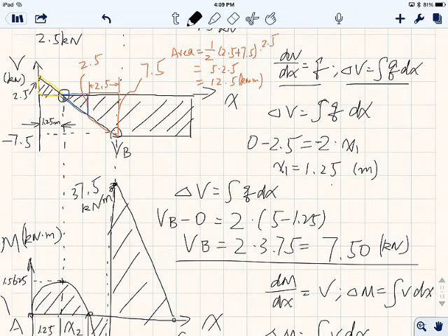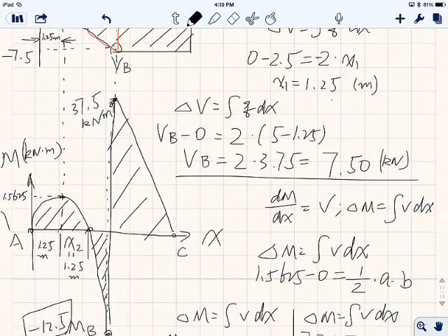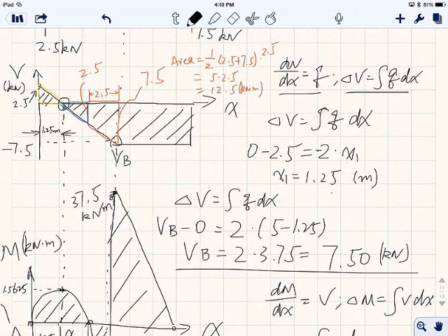So, like I mentioned, when we do this free body diagram or shear force bending moment analysis, there's one piece of information we can get. It tells us what's the maximum shear force existing in the beam and where it is, right? For example, this case tells us the maximum shear force is minus 7.5, existing from point B to point C. Also, it tells us the maximum bending moment is 37.5 and existing at exactly point B. Now, we know the maximum shear force and maximum bending moment.